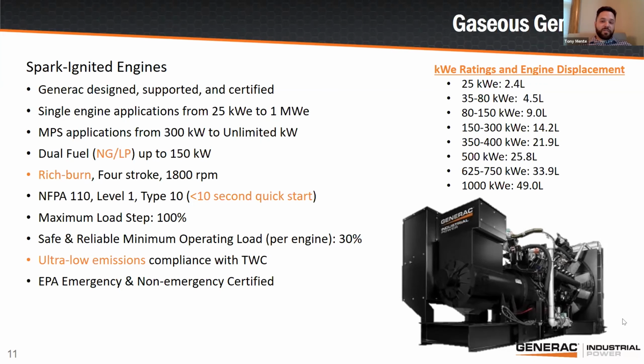Again, one of the benefits of our natural gas, besides the super low emissions I just talked about, is the ability to start up, take load, and be online very quickly. All of our products meet what's referred to as NFPA 110 Type 10, which essentially means from the time you hit the button or the automatic transfer switch switches over and says we need the generator to run, you'll be fully back, lights on and everything, in less than 10 seconds.